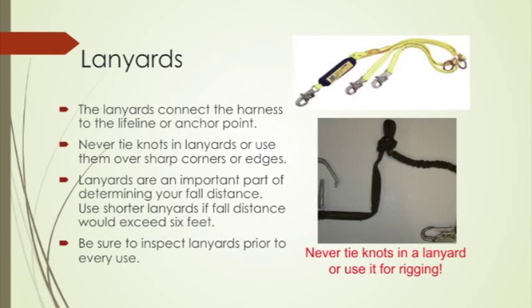Lanyards are used to connect the harness to the lifeline or anchor point. You should never tie knots in lanyards or use them over sharp corners or edges, as this will weaken the lanyard. Lanyards are an important part of determining your fall distance. Use shorter lanyards if fall distance would exceed 6 feet, and be sure to inspect lanyards prior to every use.